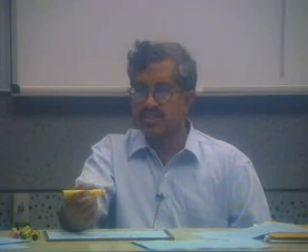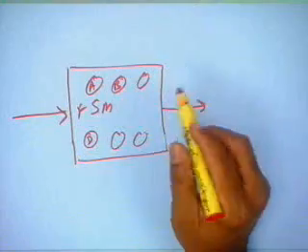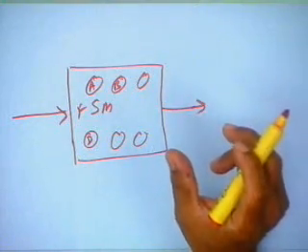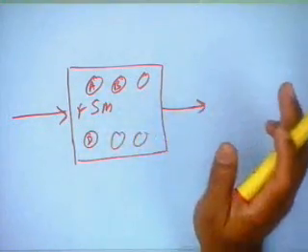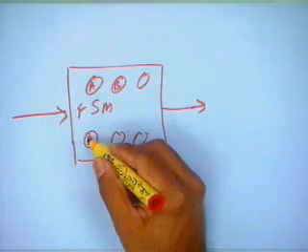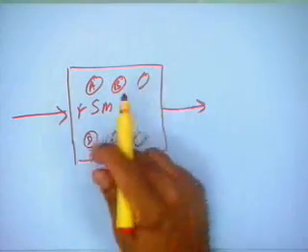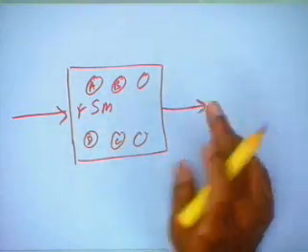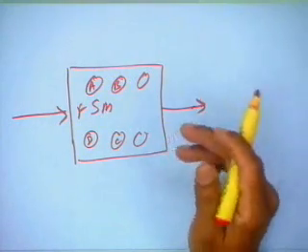So, I should uniquely be able to say, looking at this output pattern, that there is a unique output pattern for any of the final states that it needs to reach. Actually, more than one pattern may map to a state, that is a different issue, but I should be able to distinguish when, let us say, my final state is D or final state is C; the output patterns should be mutually exclusive. So, that is called a homing sequence, and we will see how we can find homing sequences. Well, now let us define a distinguishing sequence.